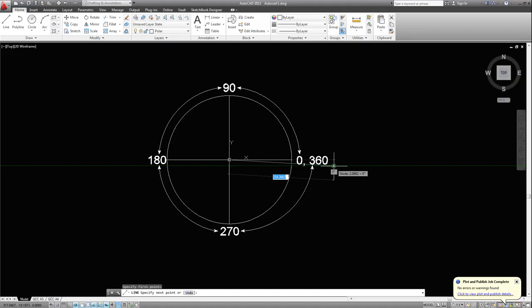I will just type this line in. The way that we can tell AutoCAD, you see down the bottom, the line, it says specify next point. I'll just escape from that and start again. If I click there, it says line specify first point. So I'm going to select that there, and where it is, that is actually 0, 0, 0. 0x, 0y, 0z.